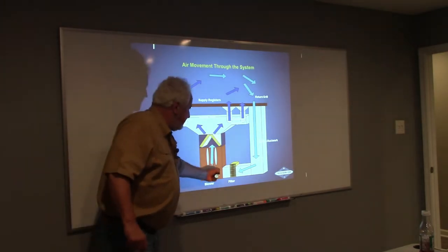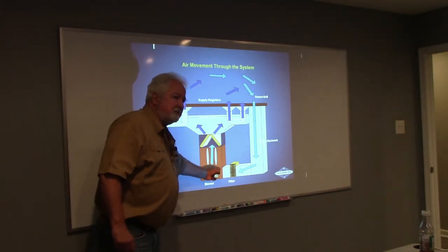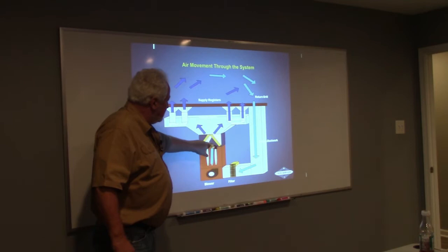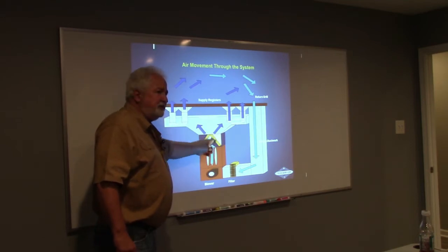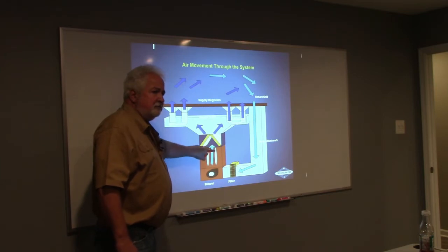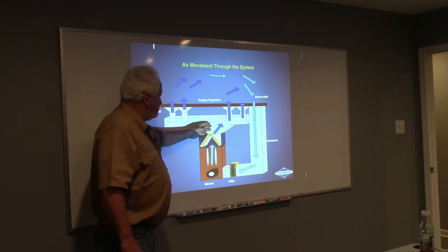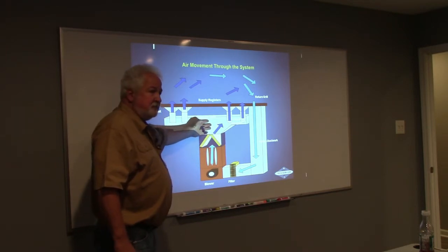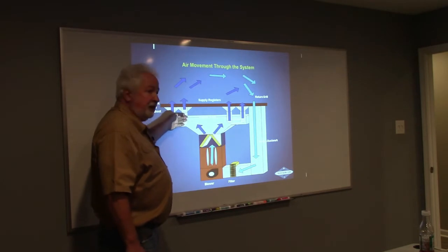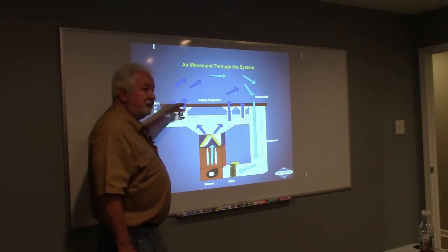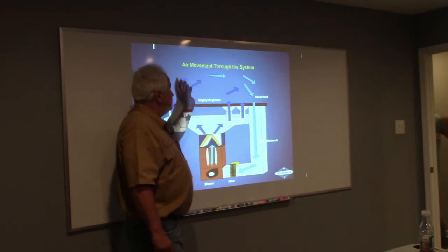All right, so air movement through the duct system. It starts here. This is your lungs. It blows across the heat exchanger, blows across the coil. Is the coil resistance to airflow? Absolutely, yes, there's some resistance in there. Okay, what about the ductwork? Is that resistance to airflow? Yes. What about the branch ducts? Yes. Good. What about the grills? Yes. Good.